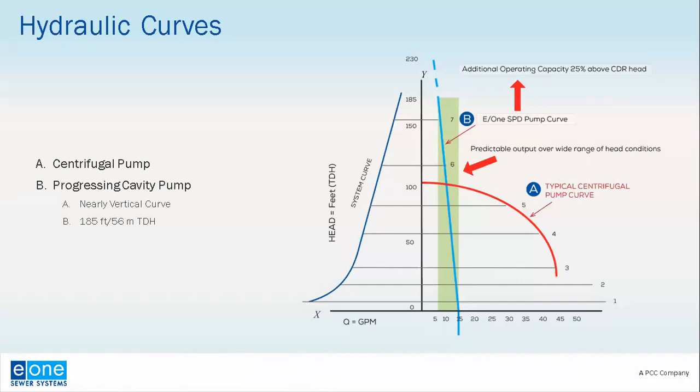So what does this mean to you? Well, it means that this is a pump that is going to work in an incredibly wide range of applications and conditions. This is residential low pressure sewer. These are not lift stations. You should not have pressures up around 80 or 90 PSI. Typically, we're going to see them even in high pressure situations at 40 or 45 PSI, somewhere in there, certainly well within our range of capabilities.